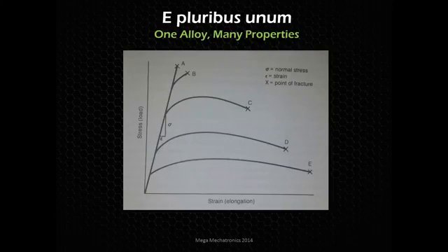So imagine this is one type of metal, one type of alloy with certain elements. We're not changing anything. The only thing we're changing is the treatment. So A, as quenched. This is straight out of after you heat it up to crystallization, you quench it in that water, and it's super brittle. It is strong, but it's so brittle. And you don't want to leave it, especially in a manufacturing environment when you're moving parts around. You don't want any cracks to form, people banging stuff around on the high-low truck.